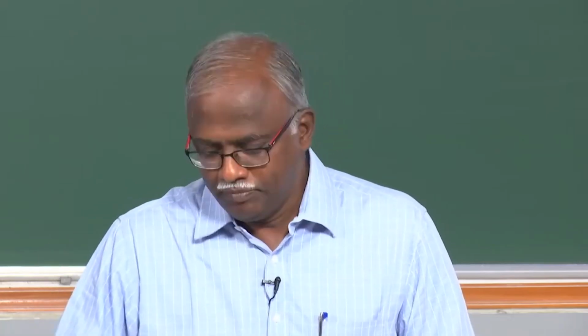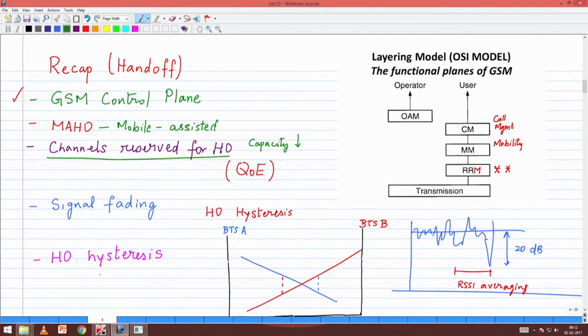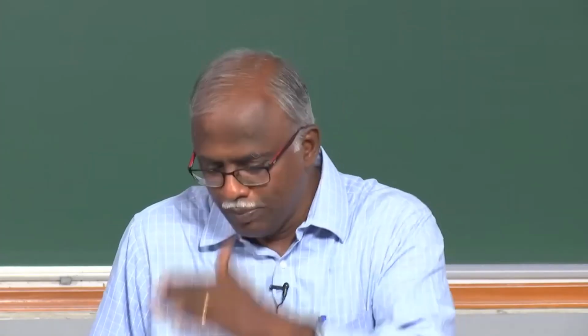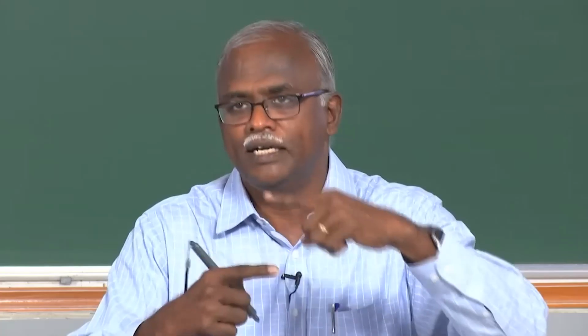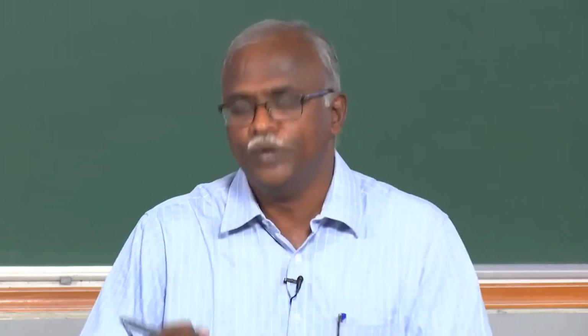Even on top of that, we do not want a phenomenon known as ping pong handoffs. You don't want to say, hand over me to B, then again say, no, I want to go back to A, going back and forth. So this ping pong handoff is something that we do not want to have, and therefore we have introduced a hysteresis. So you do not hand off until you have established that the new base station is higher by a threshold, only then you will do the handoff.